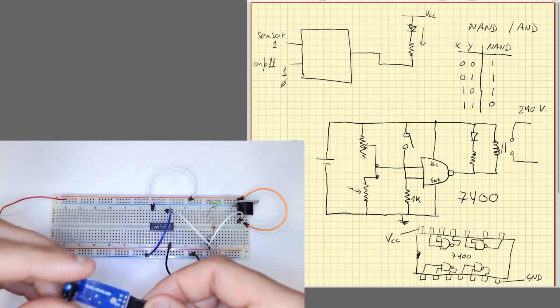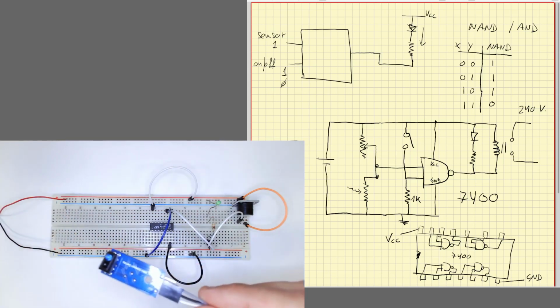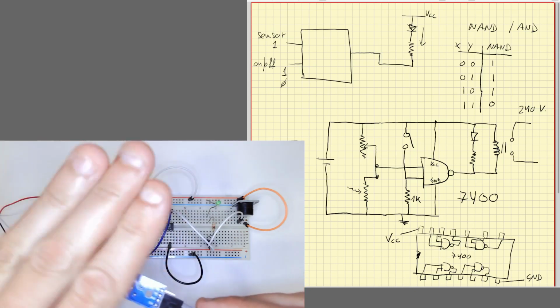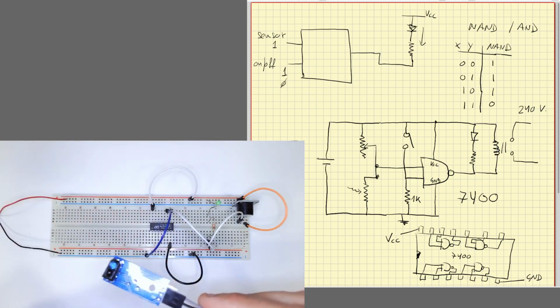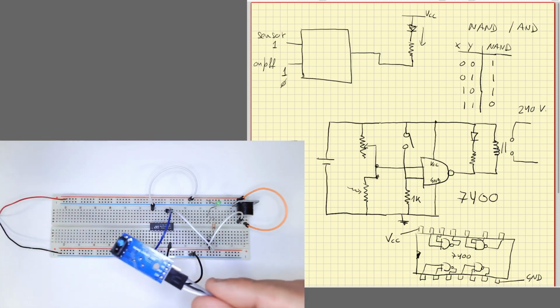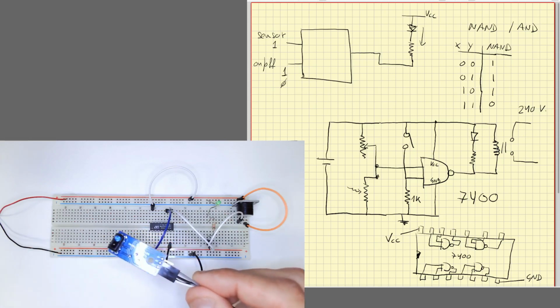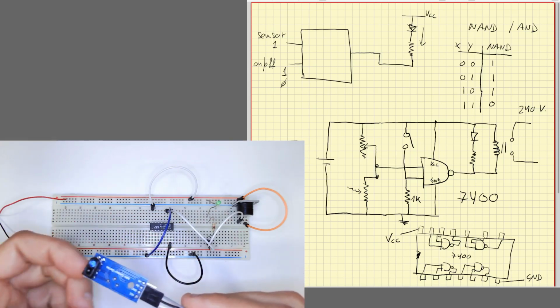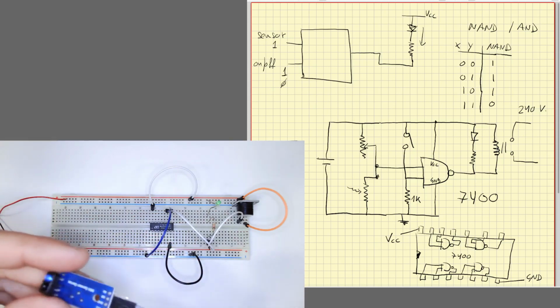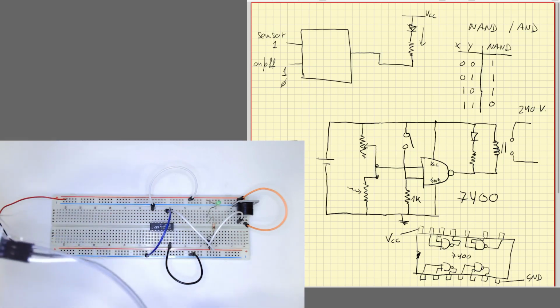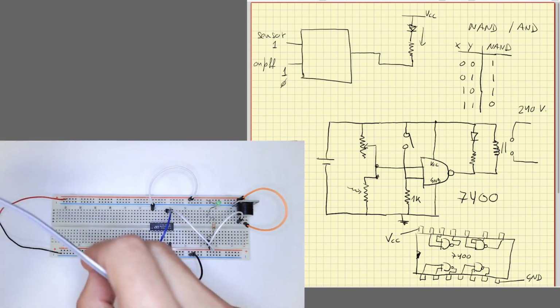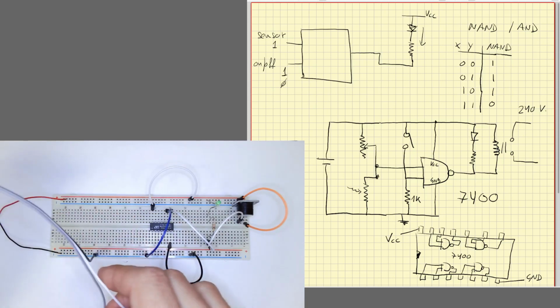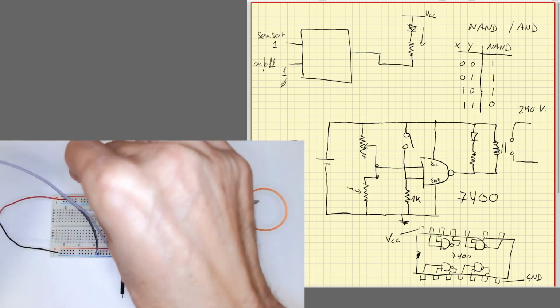Okay, the digital output will be just high or low, 1 or 0, depending if it detects something or not. Because we are interfacing to a digital circuit, it's the one we need. But it also has an analog output. If we want to detect how much light is receiving, it could be good for other applications. Okay, so now we connect this to ground, connect this to VCC.